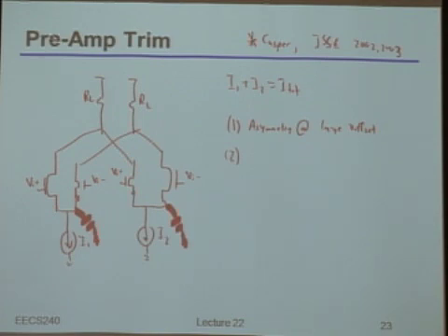Now, we just have to be a little bit careful because remember, I'm interested in a voltage range. So what's the units? Yeah, okay, so what's the magic parameter that we've used since, like, lecture 2 or 3 in this class that's probably what you're looking for? V star, there we go. So what really sets the range in terms of the offset cancellation is the difference in V star between this big device and this small device.